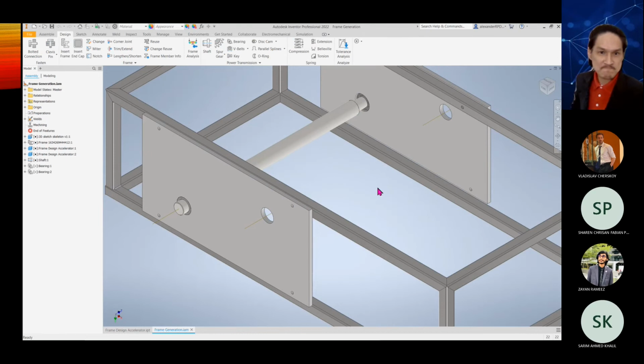In the remaining time, if you are following over here, you can do another shaft and bearing insert for this hole. You don't insert the bearing first, because the bearing needs to know the size. Unless you want to do that first, and then create the shaft based on the bearing that you want, then you insert the bearing.